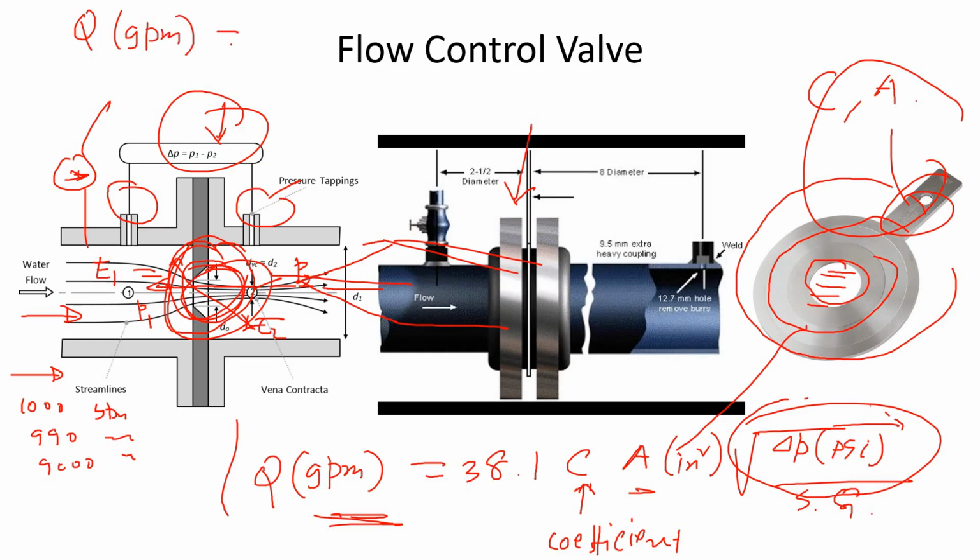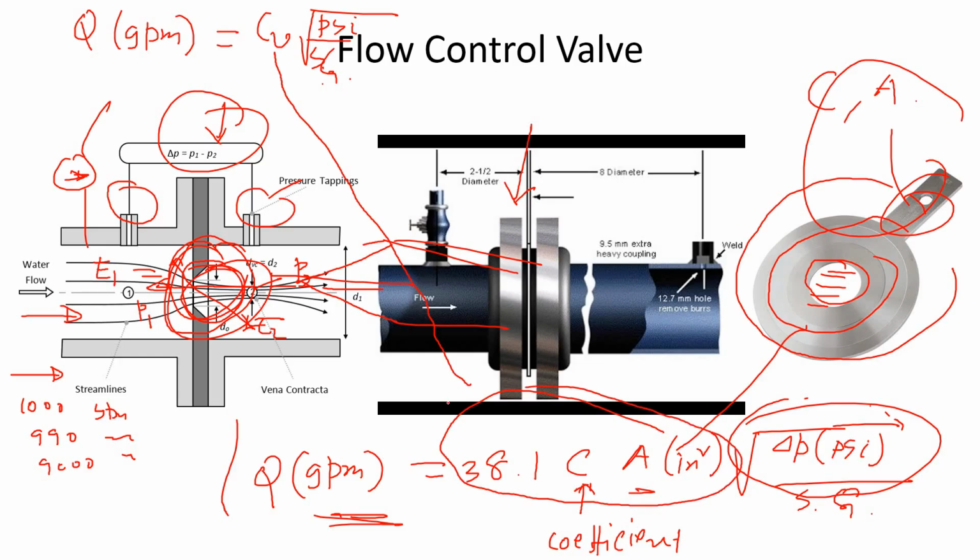So similar. However, for the flow control valve, it uses a little bit easier equation, I would say. It's going to be psi divided by SG. So for the orifice, this coefficient uses a kind of breakdown number. So it uses another constant, 38.8. Instead of that, there is a single constant for the flow control valve.